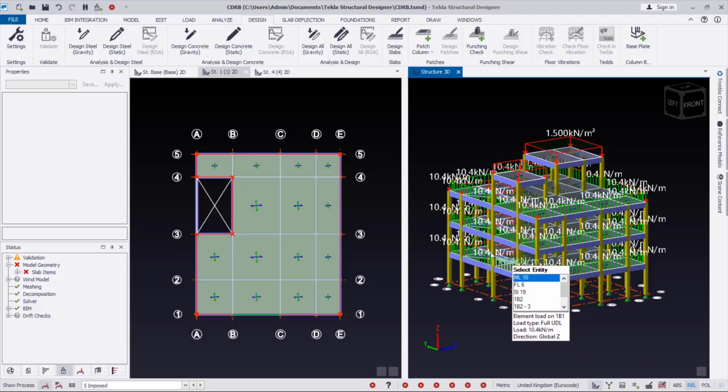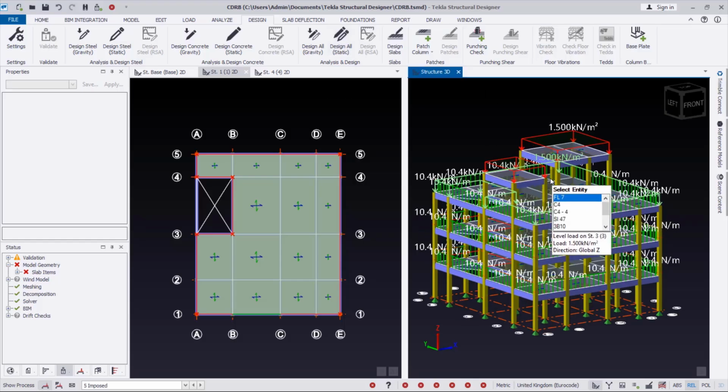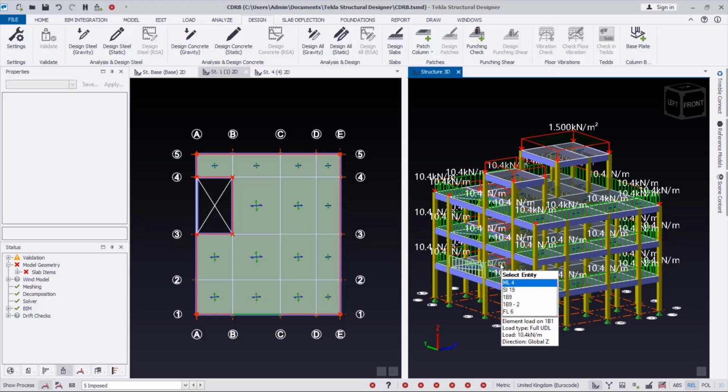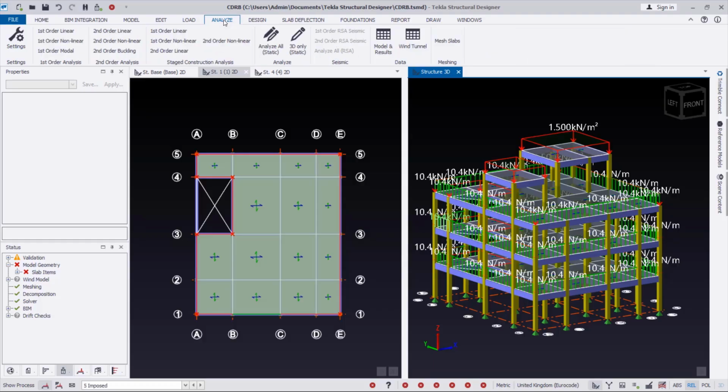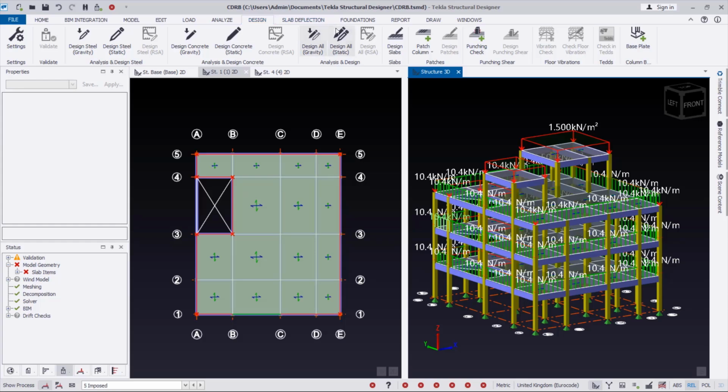Okay, it's not going to factor anything like horizontal load, you understand. But when you're using these options, it's going to factor in both the gravitational load as well as the horizontal load for the analysis and design of these structural elements of this model successfully. Okay, so the same thing is applicable to analysis over here. We just have to go to design, so we do the analysis and design at once in these provisions. Okay, so that is what we are going to do right away.